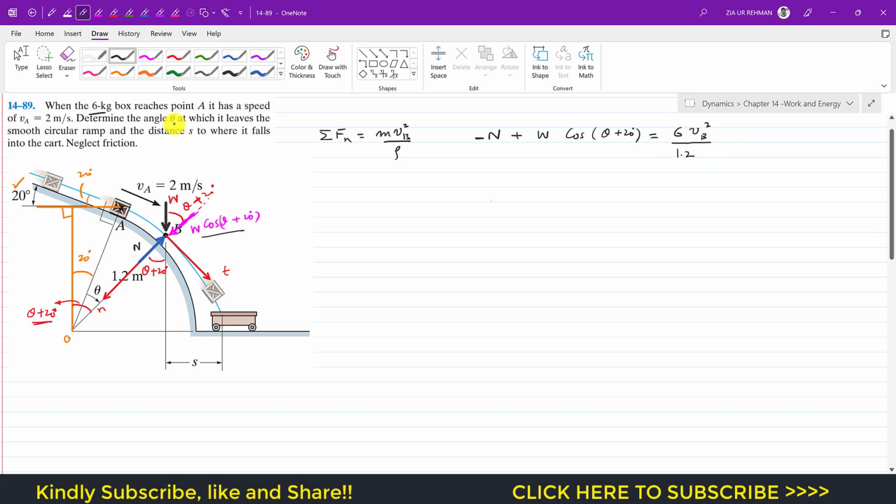Now, the problem statement says to determine the angle at which it leaves the smooth circular rim. So wherever the box leaves the surface, the normal force of the surface will be equal to 0. Let me write that N will be equal to 0. So if N is equal to 0, we are left with this equation. From this equation we can write that Vb square will be equal to 1.2 W cos of (theta plus 20 degrees) divided by 6.